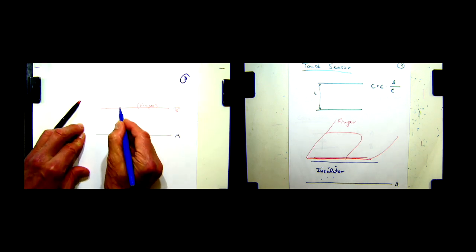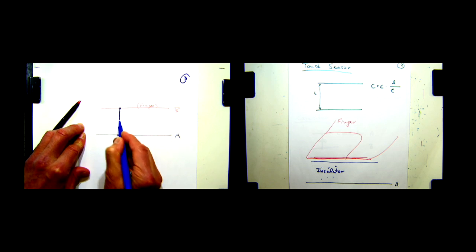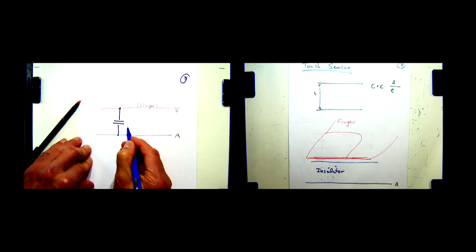this doesn't really matter. Okay. So now because of this arrangement, there is insulator in between these two plates. Well, these are two plates separated. We inherently form a capacitance C. That's just because of the way capacitance works. The minute we have two conductors, in between them we're going to have some capacitance. So as we bring our finger there, we get the capacitance. If we remove the finger, the capacitance is no longer there. So now, of course,